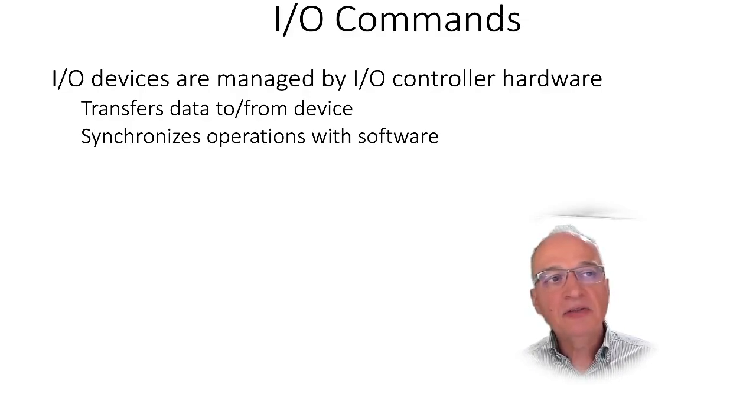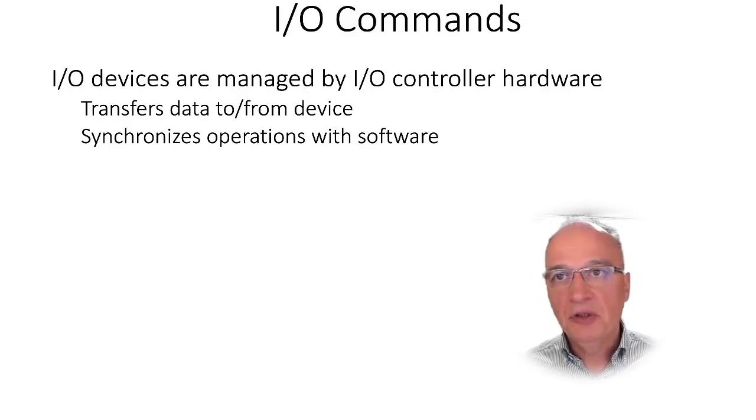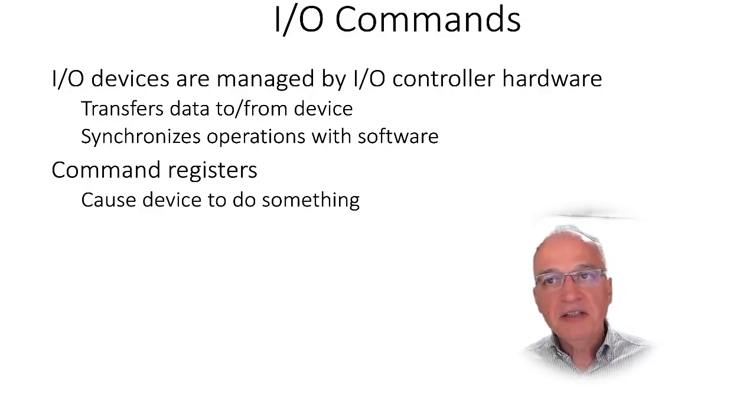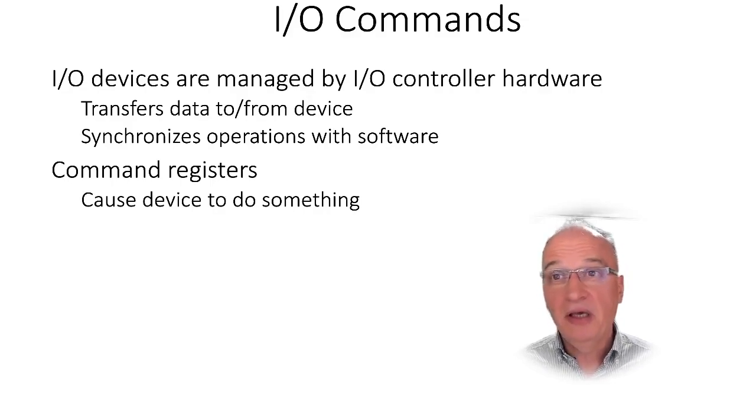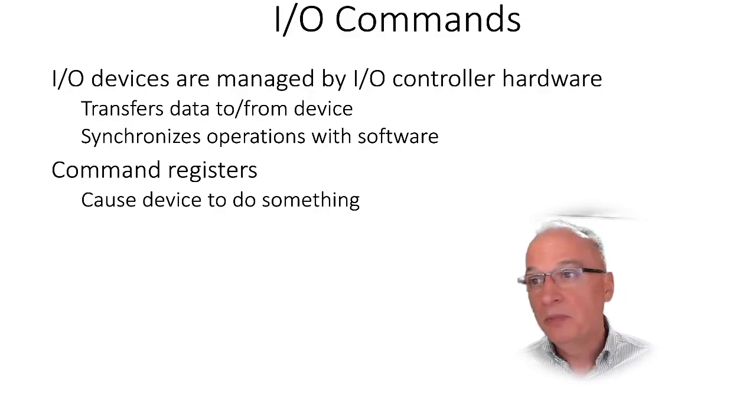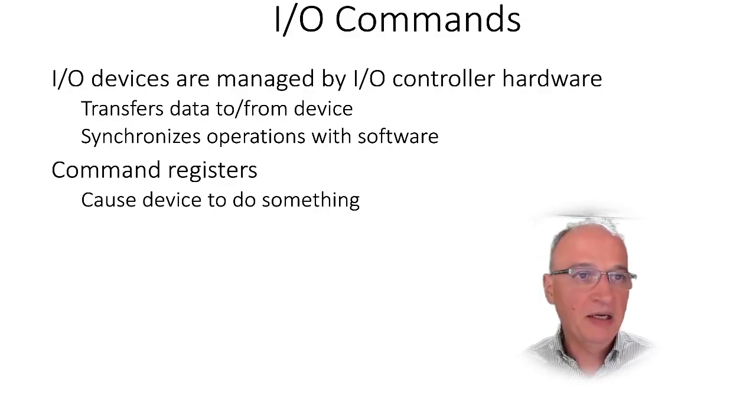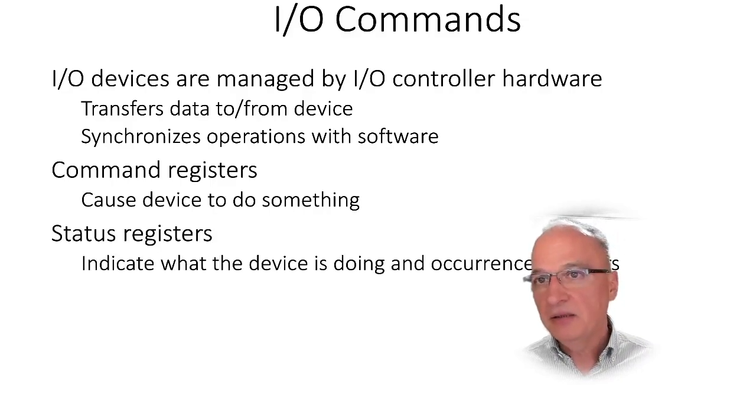And then it has to synchronize its operations with the software that's running in the computer. Command registers are registers that, when I write to them, will cause the I/O device to do something. For example, I can command a display to go completely black or something like that.